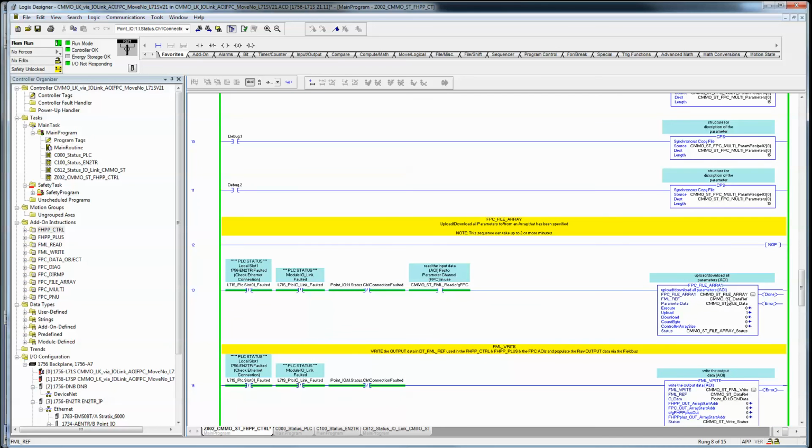Then you have this key user point here. This is a way of storing the entire project that you have configured in FCT into your PLC, so that when you do a change out, maybe you've got a problem with your drive, you basically come into here and you can write all the parameters without using FCT. So I come into here, type a 1 in, and there's actually 21,948 bytes, and this is EthIP going down to IO-Link, so it'll take a little bit of time. Sometimes it takes about 2-3 minutes.